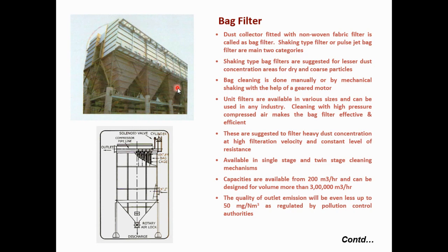If there are more dust particles, and the instrument where dust is generated is large, and the volume of the gaseous pollutant is large, then they have to install more bag filter units. According to that you have to arrange your cleaning unit also. These are suggested for heavy dust concentration, high filtration velocity and constant level of resistance.